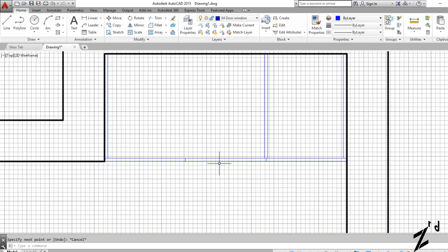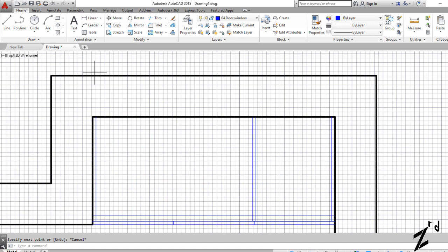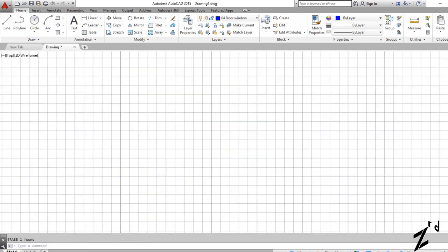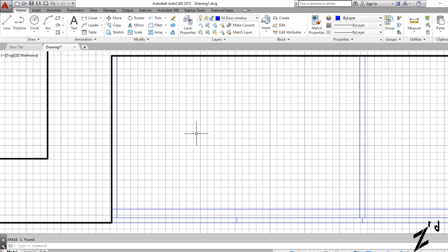I'm just going to randomly draw one there. So assuming these are three doors, that's our support. So it has to come up here. The shelf cannot come to this level, right? There has to be a decent clearance behind it. So that's let's say 3 centimeters, which makes your shelf depth 55. It's approximately 55 centimeters rather than your full 60 centimeters depth.